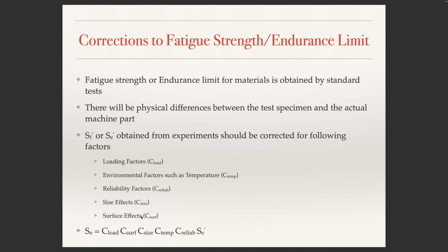And because here we are talking about crack propagation, if the surface is not clean, then you can actually have crack initiation from the surface. On a rough surface, the probability of crack initiation is much higher compared to a smooth surface. And hence you need to account for surface finish. If the surface finish here is some value, and in reality the actual component has a different surface finish, the properties are going to be different. Okay? So one needs to account for all these.